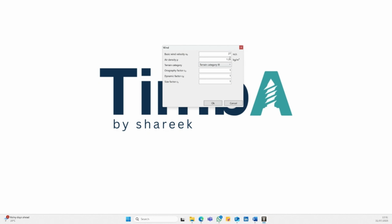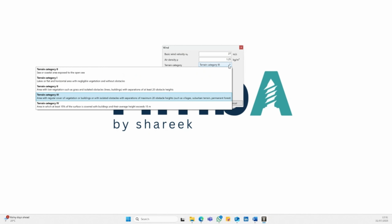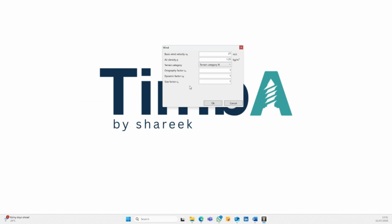And next, the terrain category. There are 5 terrain categories to choose from. Each one represents a different type of surrounding environment, like open fields, suburban areas, or city centers. After that, we'll need to include a few more factors. Orography, which accounts for hills or slopes. Anemography, which relates to wind measurement data. And the size of the structure, which affects how wind loads are applied. Once all that's filled in, just click OK to confirm and move forward.